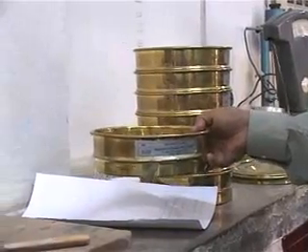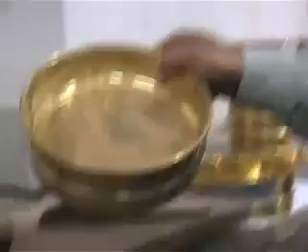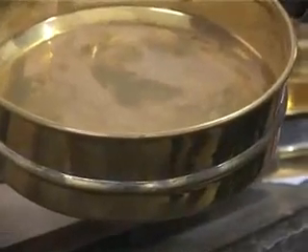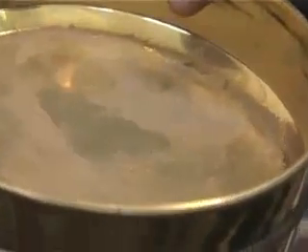Okay, then we are going to proceed to the other sieve sizes similarly. You can see here that there is a little bit of soil retained past the 75 micron sieve, and the grain size of this particular fraction is typically not determined from sieve analysis. We are going to need another laboratory experiment, involving a hydrometer, for finding out the grain size distribution of the fraction of soil which is finer than 75 micron.